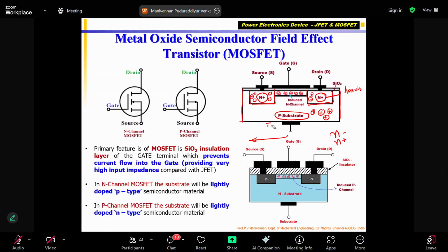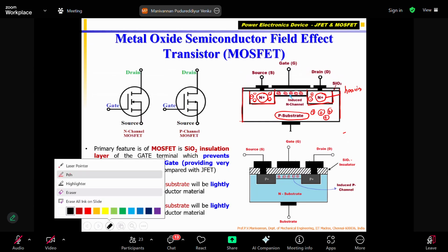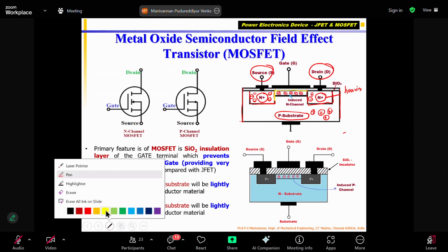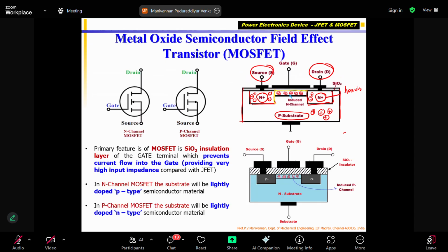The whole idea of what we are talking about here is how the MOSFET works, that's what I told you. It has a P substrate on which 2 wells are created, which are filled with heavily doped N plus. They form the drain and source of the MOSFET. And then in between, you can see here the P substrate. This area is nothing but the P substrate only. I am painting. Correct. So this whole area is also yellow color. This is also actually the P material.